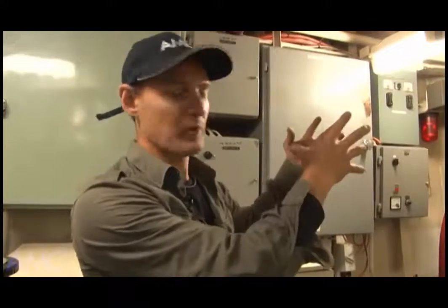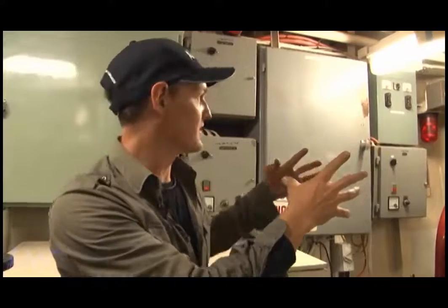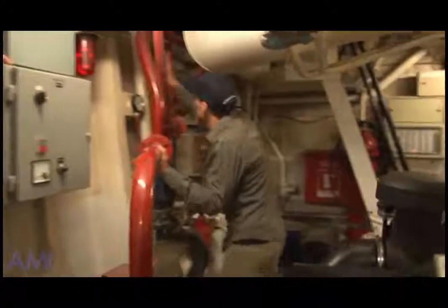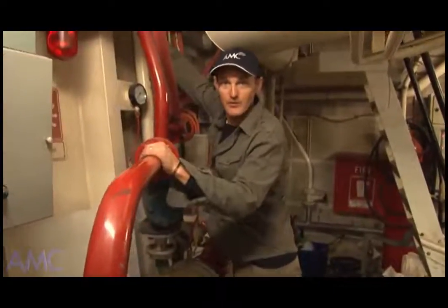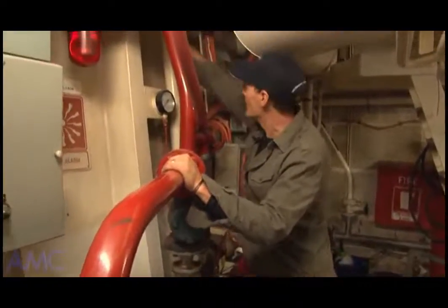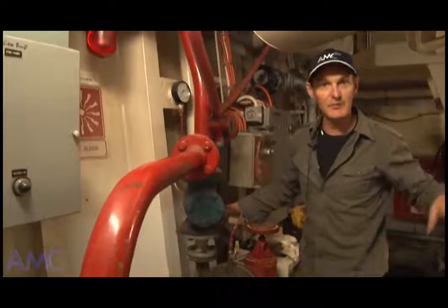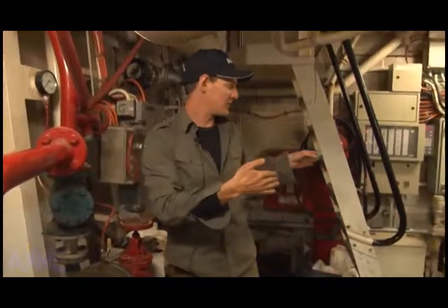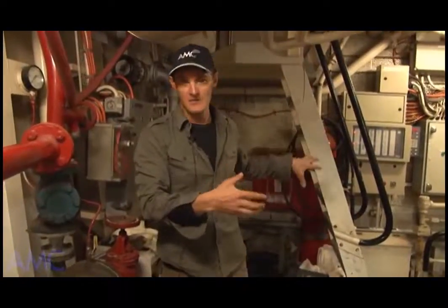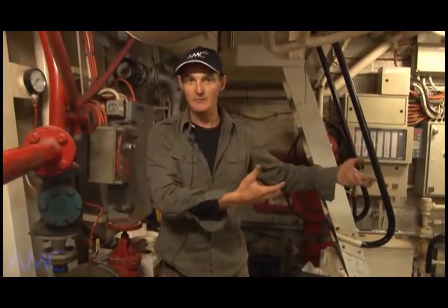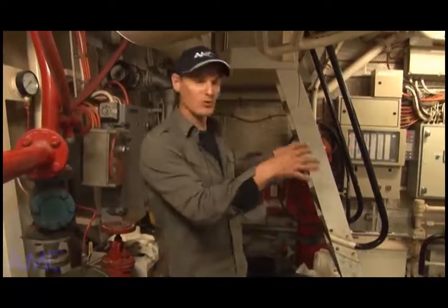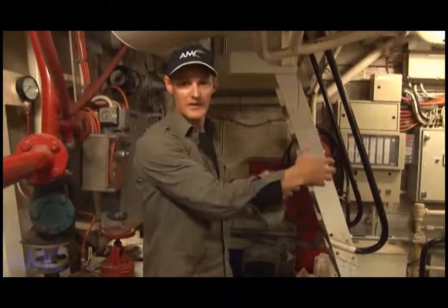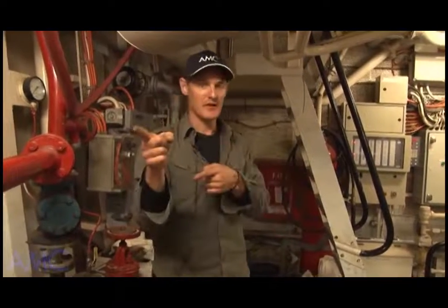We had a look at our fill point from our bunker station, and you can see it's this one right behind me, and this is dropping straight down from our portside fill point and drops down here. There's a similar one on the starboard side. They both meet up and go into our bunker suction valves. So the one valve, our quick closing valve, is the fill point and the suction point for our transfer as well.